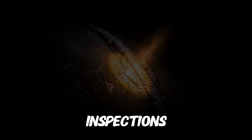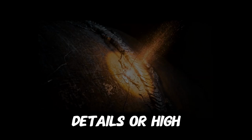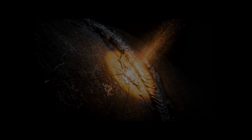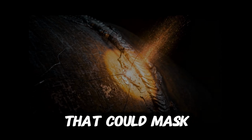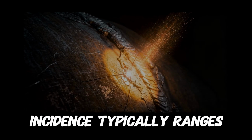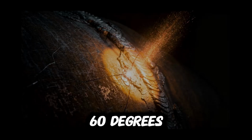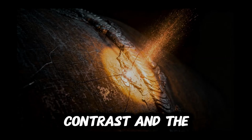First, illumination. The standard ISO 17637 specifies a minimum of 350 lux for general inspections and up to 1000 lux for critical details or high-demand welds. Lighting must be diffused to avoid specular reflections that could mask cracks or porosity. The angle of incidence typically ranges between 30 and 60 degrees relative to the surface to maximize discontinuity contrast.